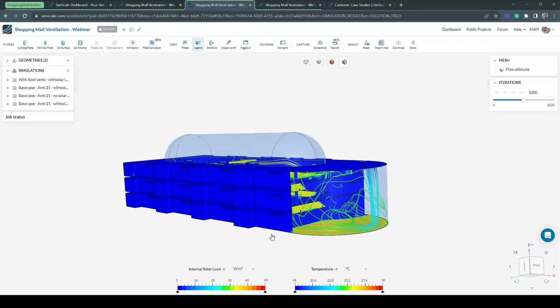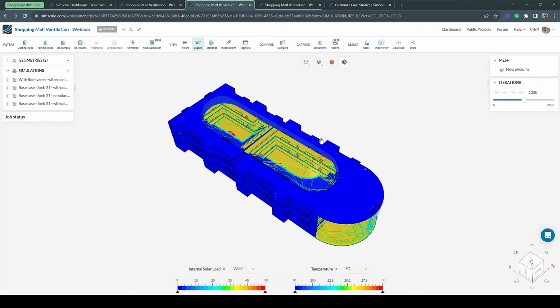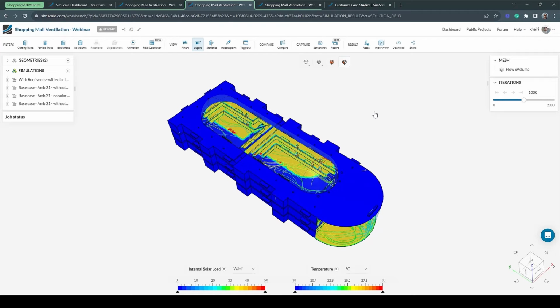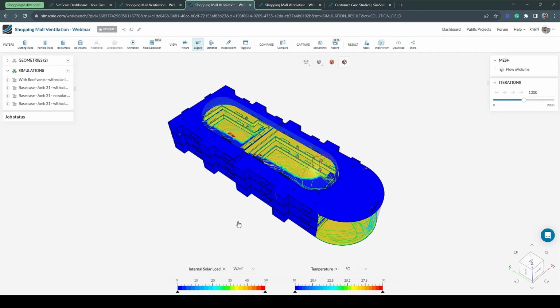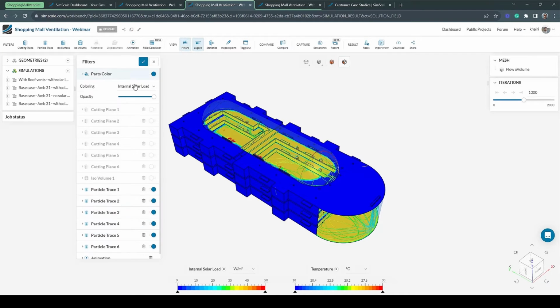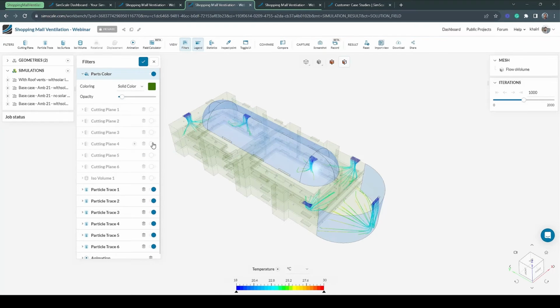Moreover, we can take another look at the other surfaces that were affected by solar load. So essentially the solar rays again were coming from this particular angle, and we can clearly use this information to identify, at a certain time, on a certain day, what areas of concentration would be affected the most and so on. Now, further insights can be gained from this simulation by making other plots that show the overall temperature distribution, let's say, inside the space.